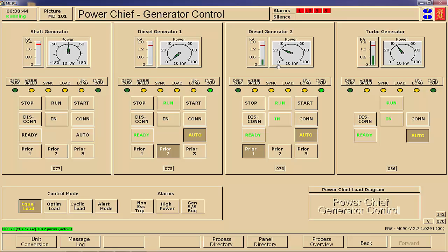and a diesel generator. The reason I'm doing this is the bow thruster. When you're running the bow thruster, if the pilot and the captain, or it's really the pilot, if you're overusing that bow thruster, if you use very large commands, you can overload the electrical system and you can have preferential trips or a blackout of the plant.